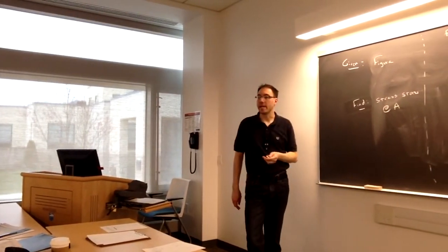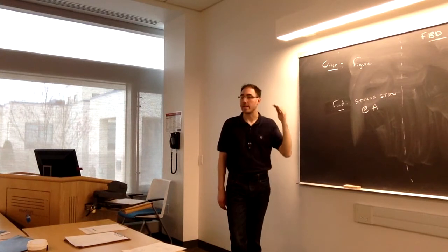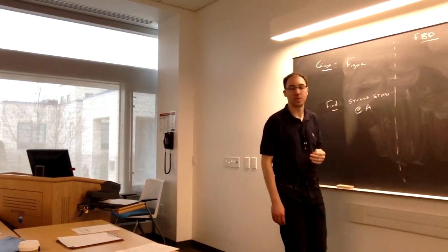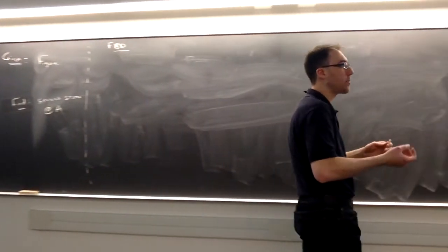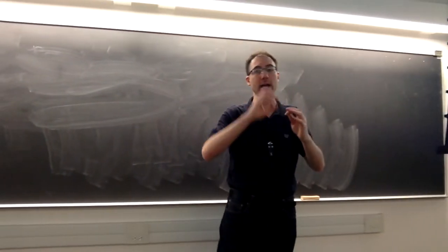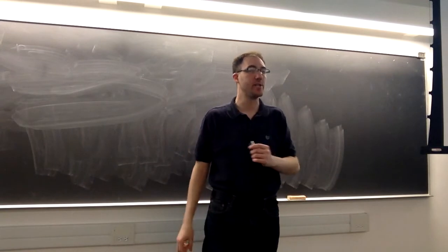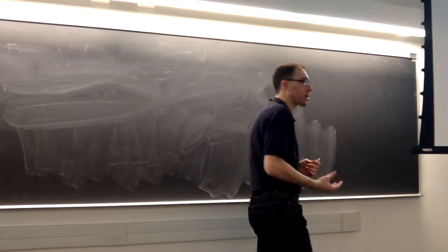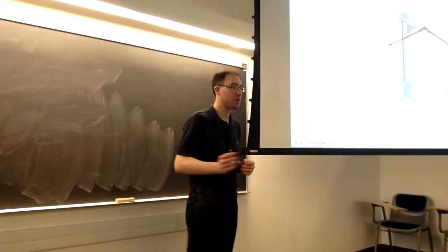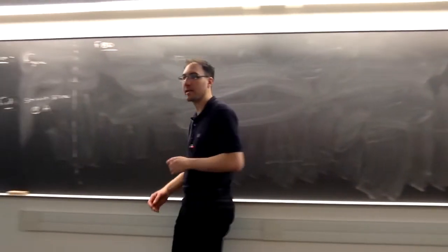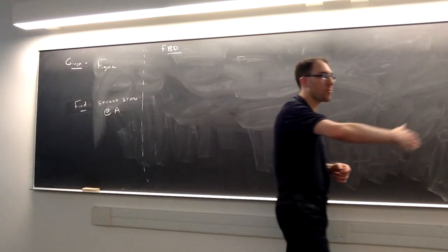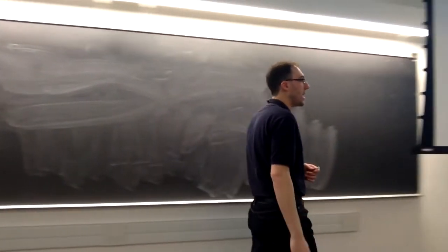So the first thing we need is to know what the internal loads are at that section. So we start by cutting through the plane. Then once we're at that plane, we go inside the cross section and see at what point we need to know the stress. Because the loads occur on a cut plane, stress always occurs at a point in that plane, because the stress can vary from one side of the opening to the other in some cases.